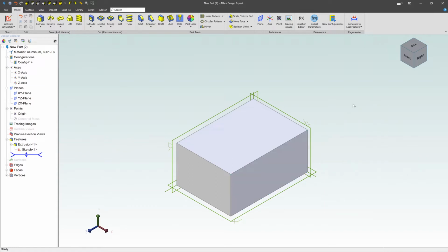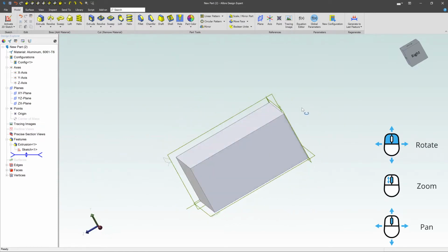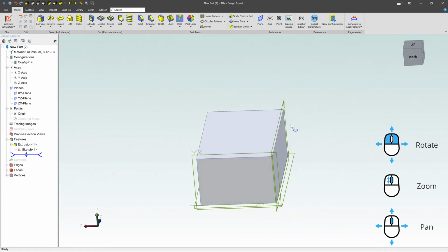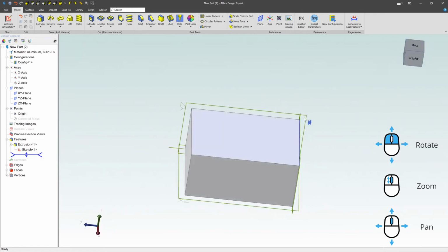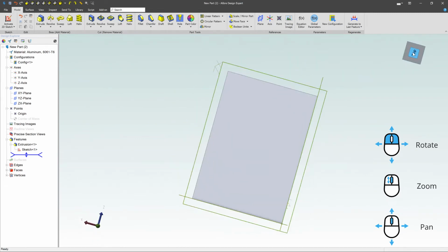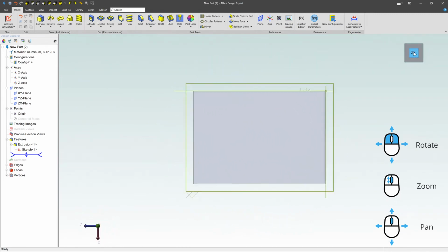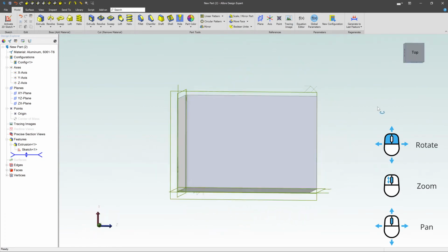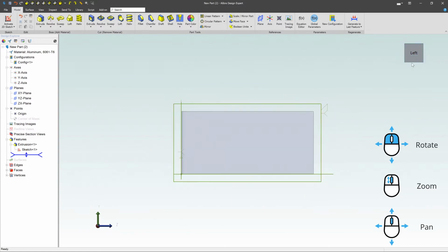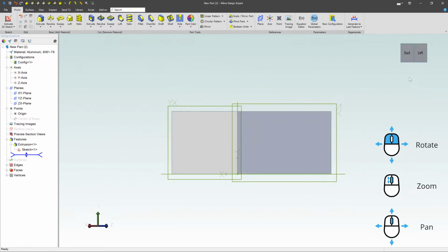Now, if you want to rotate the model around, you hold down your left and right mouse buttons at the same time. Click on both of those and I can rotate the view around. Right, so I can do that. And notice that little block on the upper right hand corner is doing the same thing. Now I can also just choose a face, like the front face. And if I click on it again, it will rotate and keep spinning. So I can look at it in different ways, right? I can then spin it around again. If I want to look at the left face, I can click over here in the center. There it is. If I want to click over here, I can spin it in that orientation. So it's really handy to kind of see.